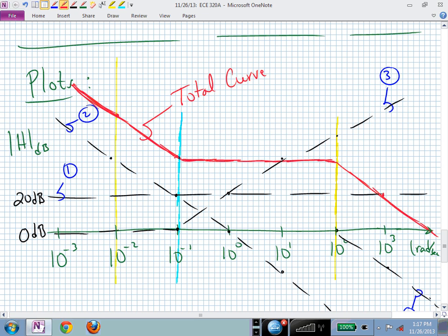In absolute terms, what's your gain? 100. So now if you put in a cosine waveform at, let's say, 10 radians per second, and it had a gain of 2, so you say 2 cosine of 10t, what's the output, sinusoidal steady state? 2 times 100, 200 cosine of 10t.